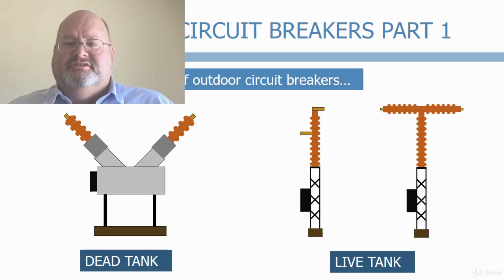Nowadays, dead tank circuit breakers tend to be used on circuit breakers up to 66 kV. Above this level, the cost advantages of live tank circuit breakers come into play, even when we take into account the cost of the additional current transformers. Above 132 kV, single-phase circuit breakers tend to be required, and therefore we have to choose live tank circuit breaker designs.